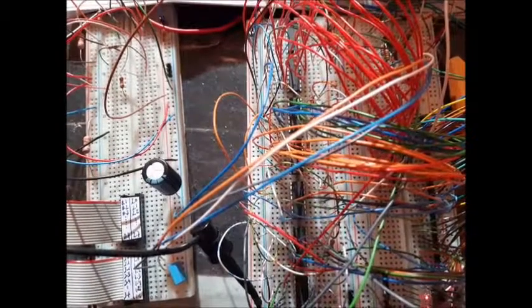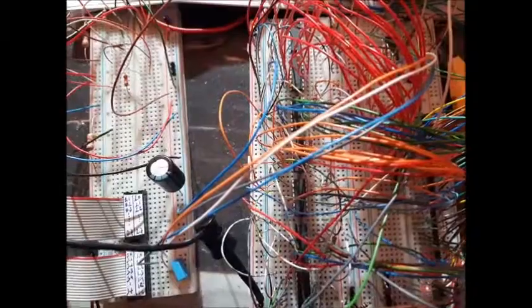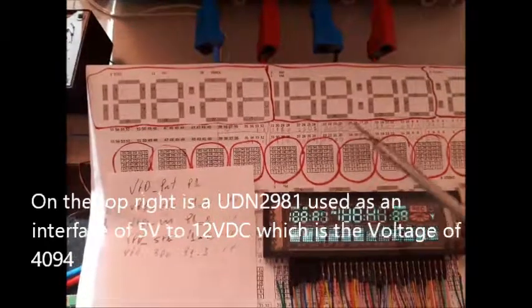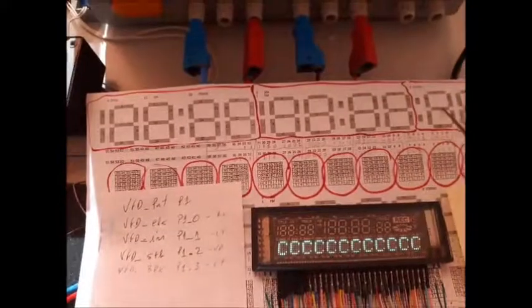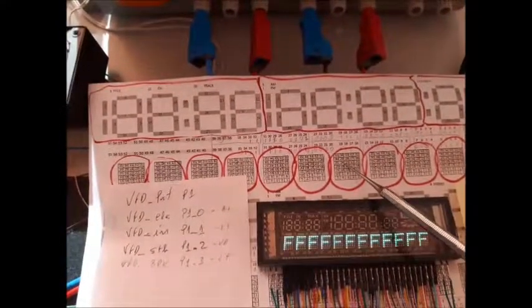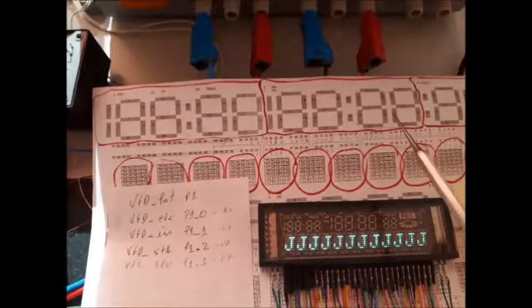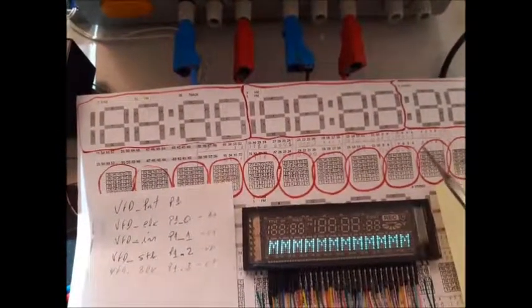I'm using 7 ICs because I need 55 ports to control all of the pins, because the total of the anodes from this grid, this and this and this, is a total of 55 pins, okay. 15 pins for the grids and 40 for the anodes.